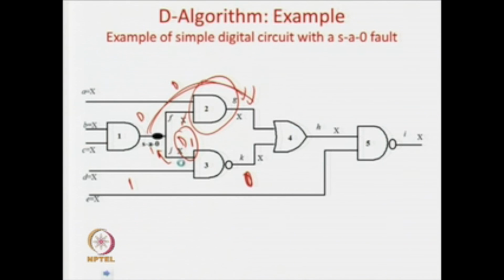So, somehow if we could have deferred the conflict to the primary input and beyond, then we could have been very successful. That is, the philosophy is that keeping more x's will delay your conflicts. So, if you can somehow delay your conflicts to a reasonable amount of time and pass it to the primary inputs, then your problem is solved.